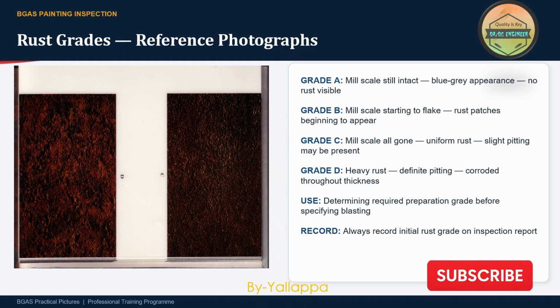This slide presents the standard rust grade reference photographs. These photographs serve as the visual benchmark for inspectors worldwide. Before specifying surface preparation requirements, inspectors must identify the initial rust grade. Accurate rust grading ensures proper selection of cleaning methods and quality requirements.